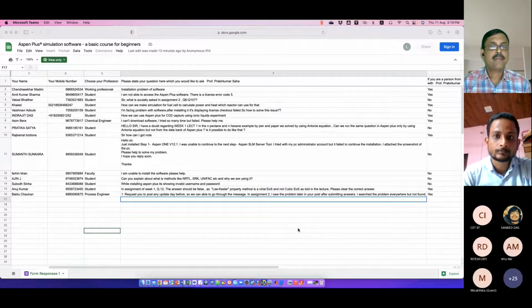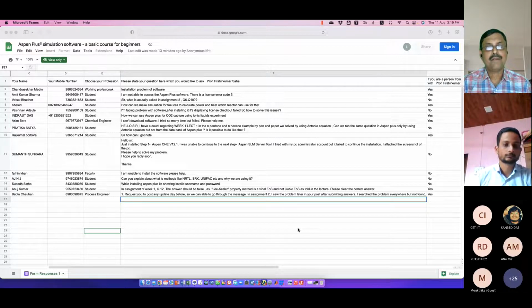But always remember, the property method assistant will suggest a method. It will not solve your problem in choosing your method. The choice of method is in your hand because you are the chemical engineer, not Aspen. You can ask Aspen to use a particular property method, but you should not expect Aspen to solve your problem. Aspen does not have any brain. Aspen is just a tool.